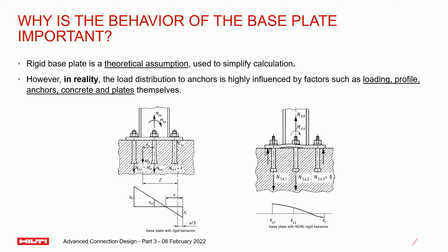Really not. In reality, your base plate has a tendency to uplift, like you are seeing on the right-hand side. The design of the base plate is highly influenced by what kind of loads are applied, what the material of your profile is, the rigidity of each different element in the base plate, and the stiffness of the material. Stiffness is a really big differentiating factor in every material. All of this comes into play when you want to look at how a base plate realistically behaves, and all of it makes the behavior non-linear. Now we will start to talk about how we handle this behavior. What are some of the applications that might be affected, for example?